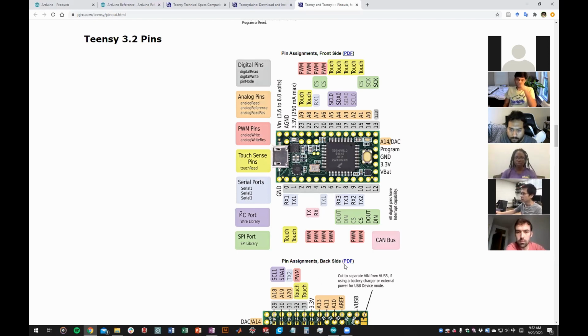If you look from the Zaber motor's point of view, the Zaber controller also has RX and TX. But in that case, the TX, T stands for transmit, sends the signal out. Therefore, the TX of the Zaber controller should be connected to the RX of the Arduino, and the TX of the Arduino should be connected to the RX of the Zaber controller.